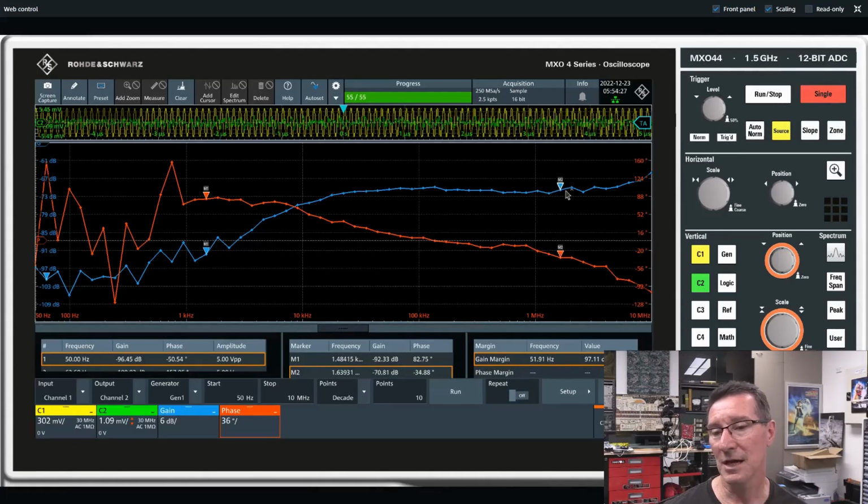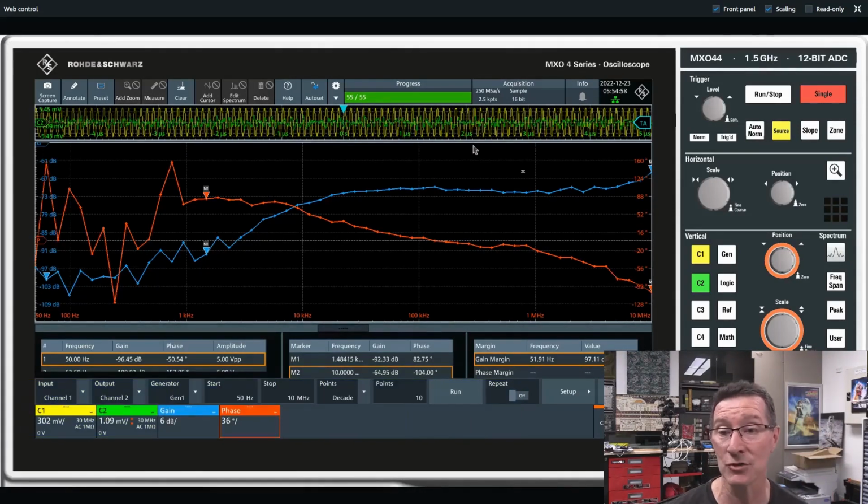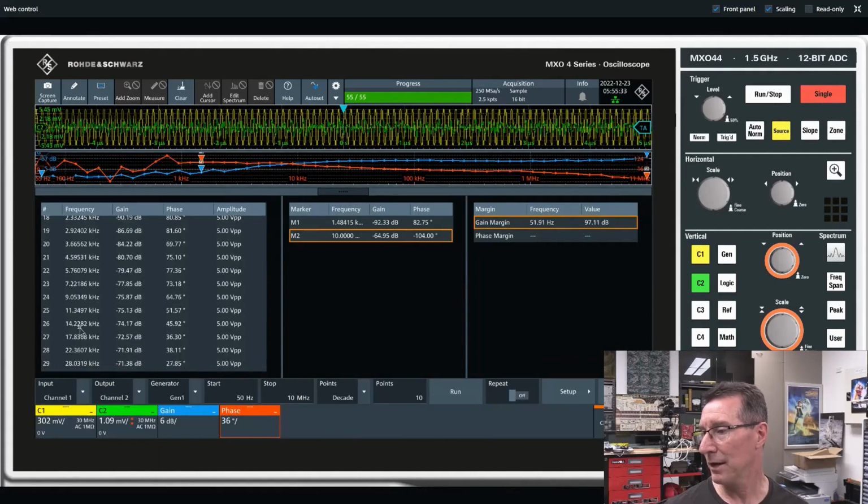You can see that around about 5 megahertz, the common mode rejection ratio gets worse. The higher that is, the worse it is. The red plot here is the gain, which doesn't matter for our common mode rejection ratio, but if we extend the bandwidth on that, we should be able to see a phase reversal. Anyway, we've got our table here, so let's go to our 10 megahertz.